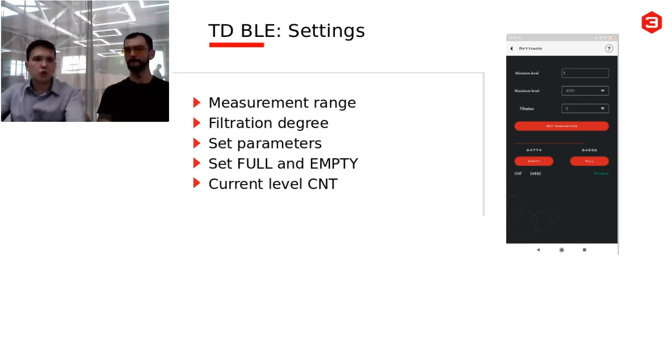In this case, you can also see that the level shown by the sensor is 7,000. This is actually a service code that lets you know that there is a short circuit. You need to clean the space between the tubes, and you'd better use pressurized air to remove everything from the space between the tubes, and flush it with clean fuel.